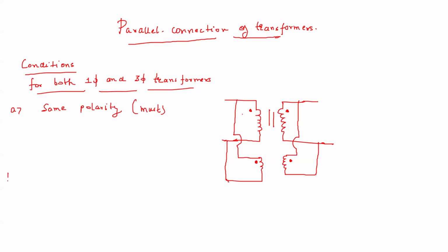Now, the second condition, which I said, is equal voltage ratios and the same voltage ratings. This is a must condition. Now, in actual systems there may be a slight difference in the voltage ratios.